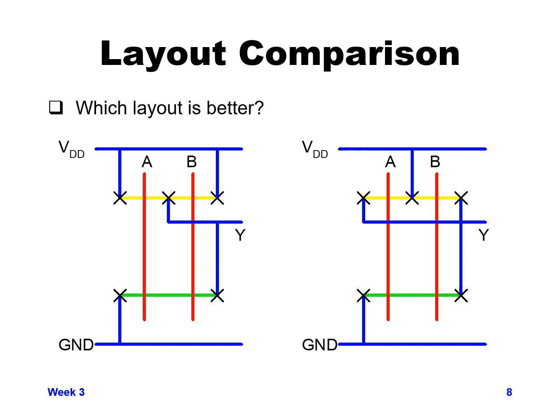So if you look at it carefully, on the left, the NMOS devices in green are identical to the right. The main difference between the layout on the left and the layout on the right is for the VDD connection and the output connection to the PMOS transistors. The layout on the left has a single contact to the output and 2 contacts to the VDD in order to get the connection of each transistor to VDD and the output.